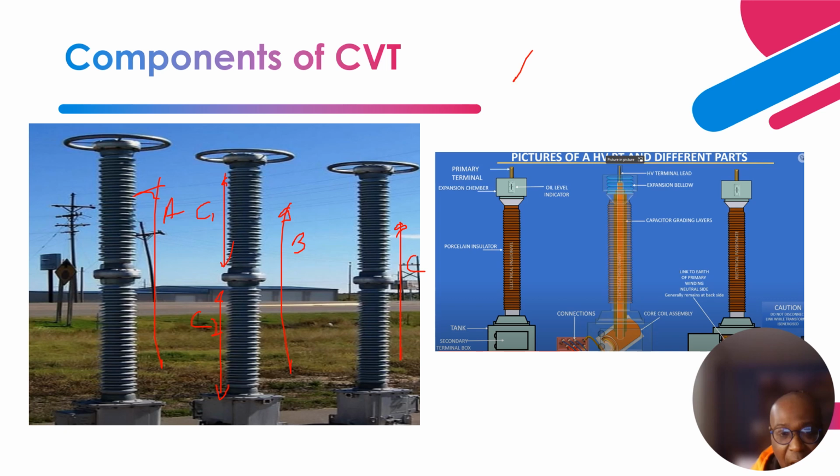So if you have a capacitor that is lower, with 1/2 pi FC, your impedance is higher, and you get a higher voltage drop across this section of the stack. This section is, like I indicated, the C2 capacitance. The C2 capacitance is much larger. So XC2, 1/2 pi FC, means that it's a much lower impedance. So the voltage drop across here is much lower. And like I indicated, that is how we are able to achieve a voltage of 10 kV.